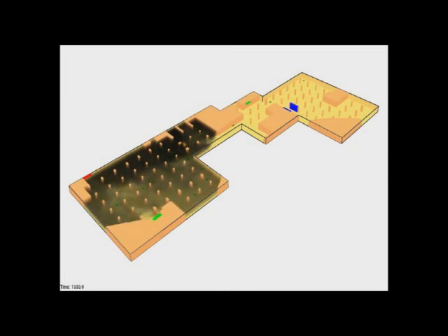There is a car here, and these are the jet fans, which are installed here as an alternative to duct ventilation. The thing about car parking is that for duct ventilation, you don't need CFD that much, because the duct will guide the smoke the way it should go. But if you have to use jet fans, then to ensure that they direct the smoke in the right direction, we need to do CFD analysis. Otherwise, the design might not be good.